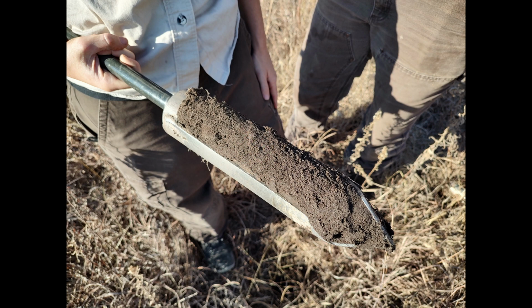The Nature Trust was not interested in restoring Nordstrom Creek where it had been ditched, so we focused on designing 4 wetlands that could be built in 2015. The test holes I dug using a 4-foot-long soil auger showed that the texture of soil on either side of the ditch was primarily silt, loam, and silt loam. I could only make a thin ribbon that was 1 inch long between my thumb and my forefinger.